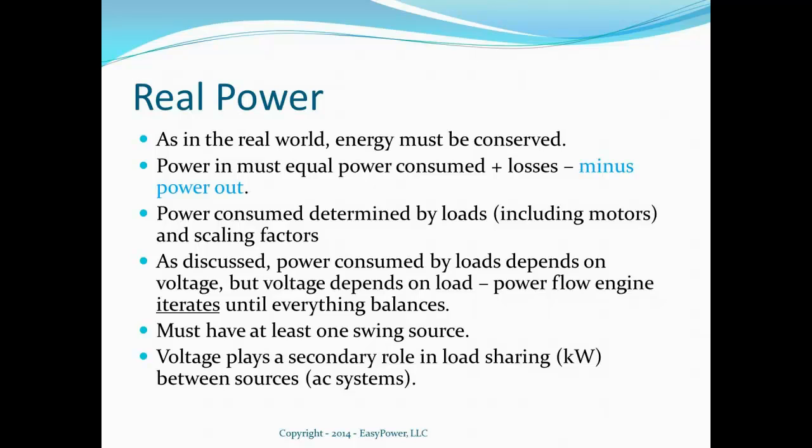And basically the power consumed is determined by your loads and the scaling factors that are being applied to the loads and the type of loads. We went through this last time, but just remember that the reason this gets complicated is because if I look at any individual load, to some extent, the power consumed by the load depends on the voltage, or it can, depending on the type of load.